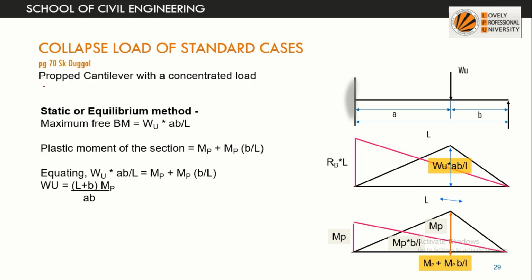Now again, a similar problem: a cantilever with a concentrated load which is not placed at the midspan. Again, we are using the static or equilibrium method, in which we equate the free bending moment diagram with the plastic moment at the section. So it is quite simple.